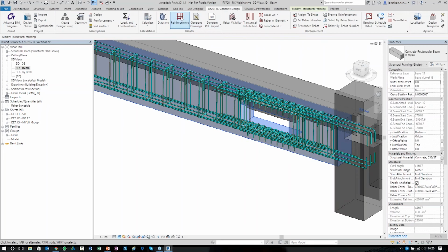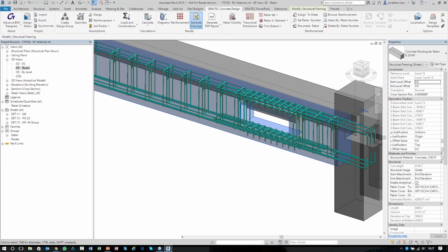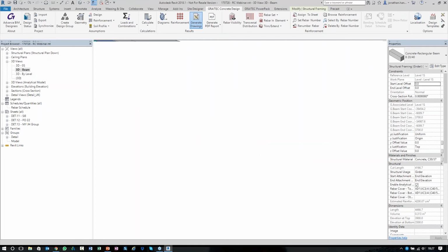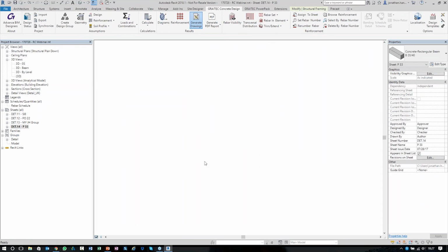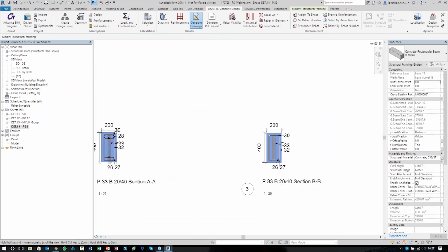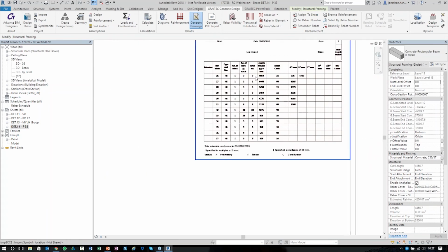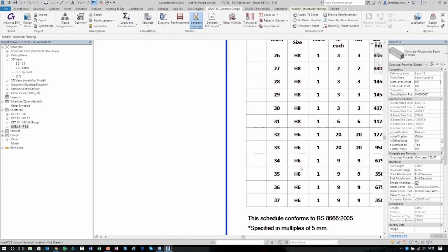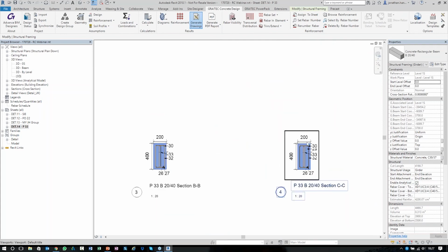So just select my footing, and we generate the drawing. So we look at detail 15, and there I have my detail view, my sections, and my schedule. And again, these views and details are all done upon a Revit template.